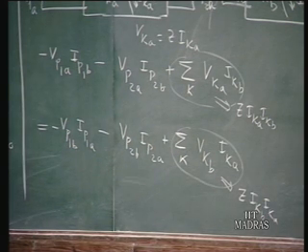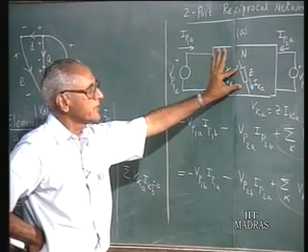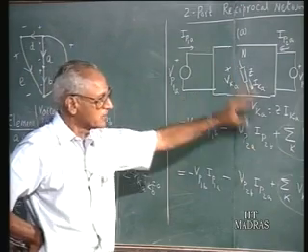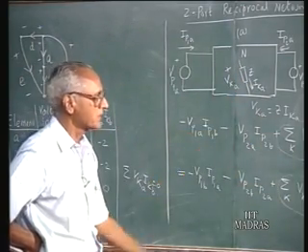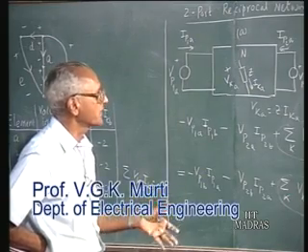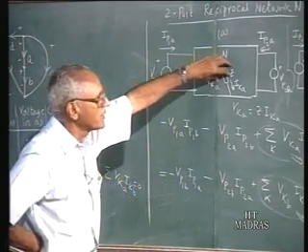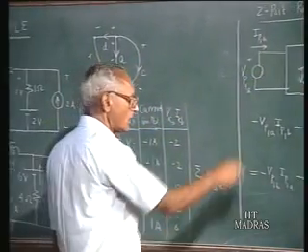What we have shown here is only for two-terminal elements. If these also have mutual inductances, which are reciprocal two-port elements, then also this particular equality will be valid. We don't take time out to show that. It can be demonstrated. Take it for granted that this will be true even if we had two-port elements which are reciprocal inside the network N. So these two are equal.